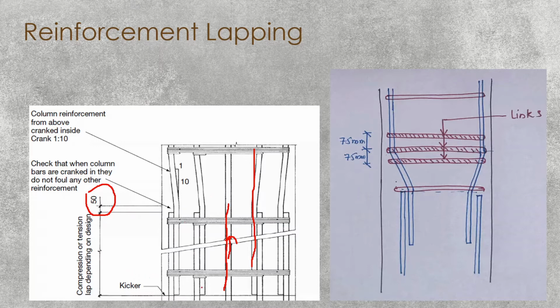And also you have to lap the reinforcement in a staggered manner. We'll discuss these things in the next slide also. Apart from that, you have to be very careful about the cranking of reinforcement. You have to maintain the standard slope.